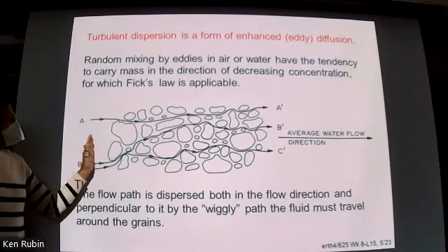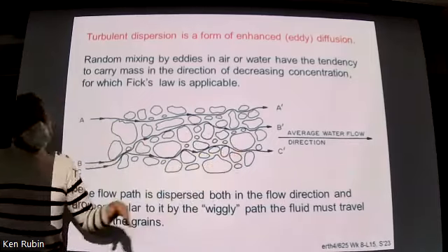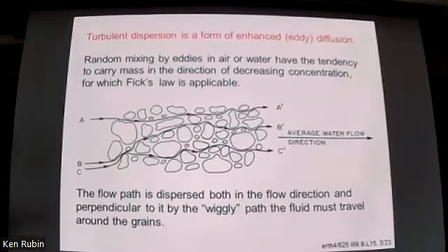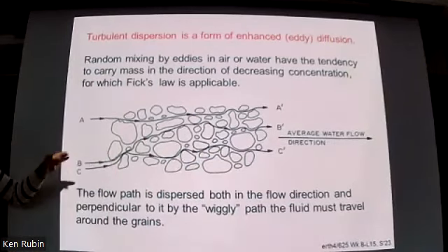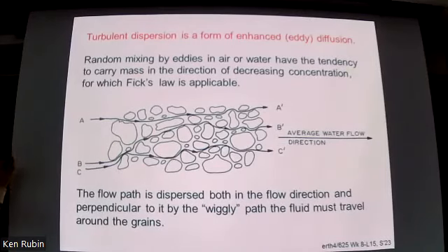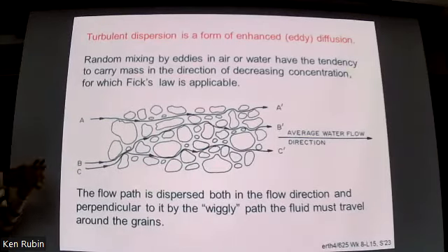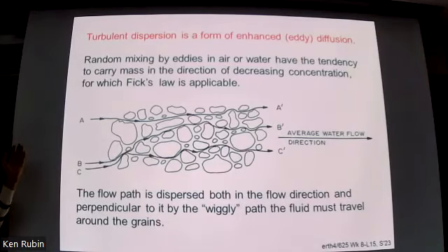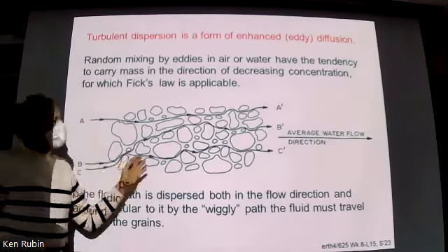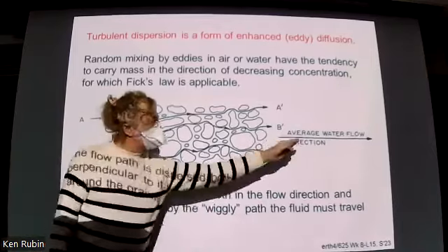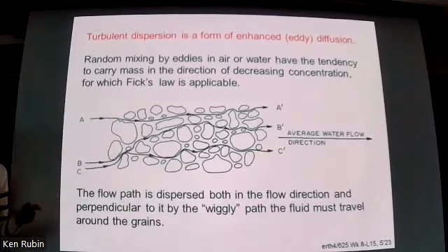So depending on the length scale over which this happens, different parcels of water will flow through this porous medium at different rates, and the solute that they are carrying becomes dispersed along the direction of flow, right? The stuff that comes through faster will, what we call breakthrough, show up downstream faster than the stuff that goes through a convoluted pathway.